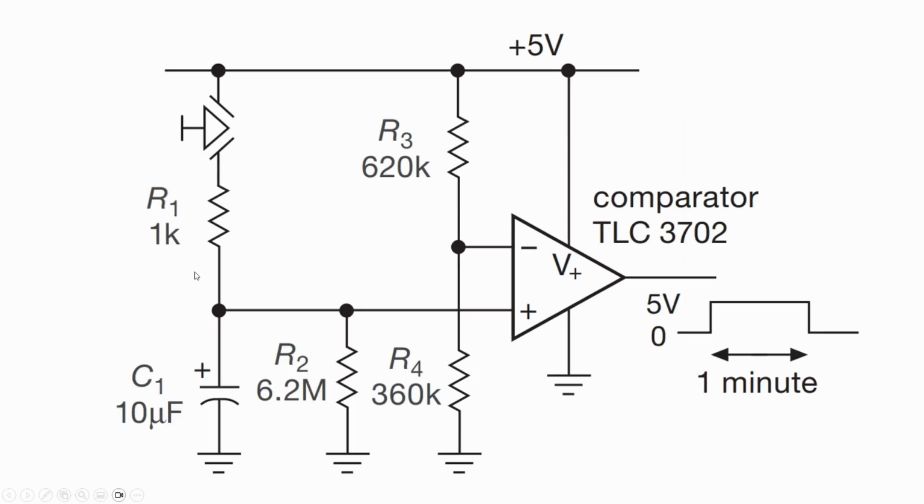So what I'm going to do now is build up this circuit. However, I don't have all of these resistor values available to me. So as I do the simulation, I will be doing the simulation with the values of resistors that I do have. Obviously that will change the timing parameters, but the circuit will behave the same way even if you are using different components. The only thing that would change is the fixed voltage that appears here, and the rate of decay on this voltage. So let's now get to the simulation.